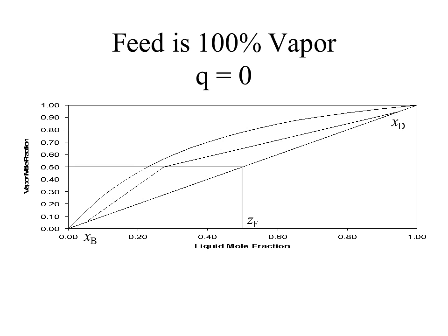So starting at xd, we move horizontally to the equilibrium curve, and then down to the upper operating line. Back to the equilibrium curve, down to the operating line. And we continue to do this back and forth until we reach the point where we cross over from the upper operating line to the lower. We can see here that we've now stepped off 1, 2, 3, 4, 5 stages, and so our feed stage would be in the 5th stage.